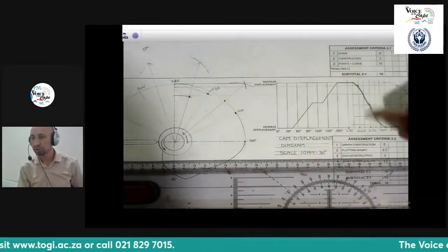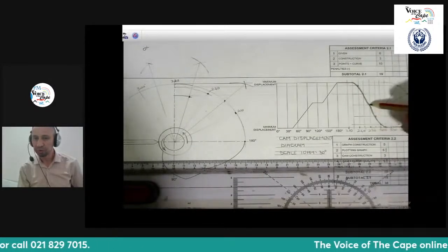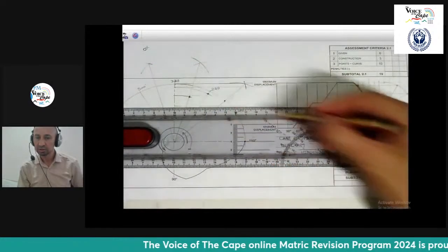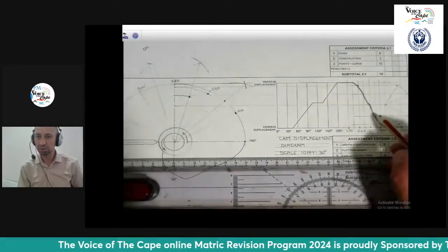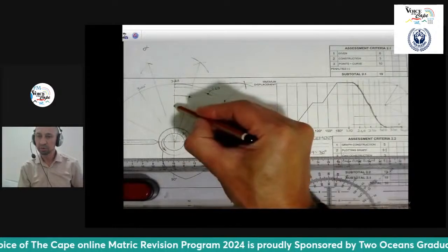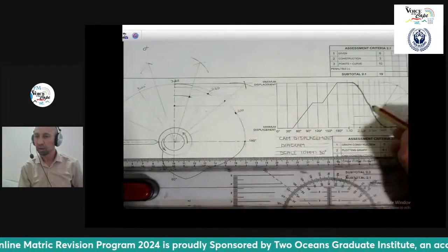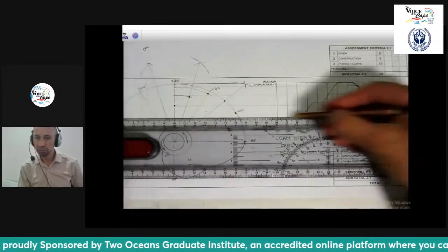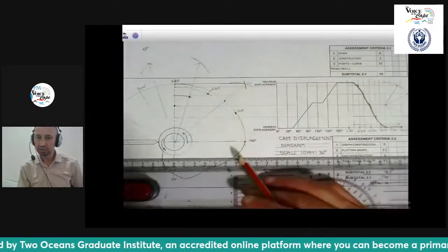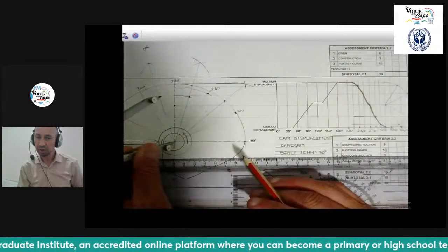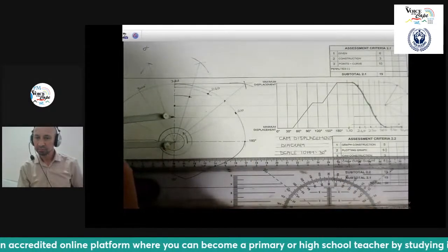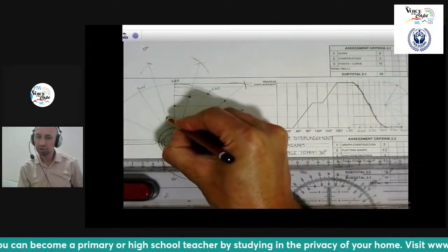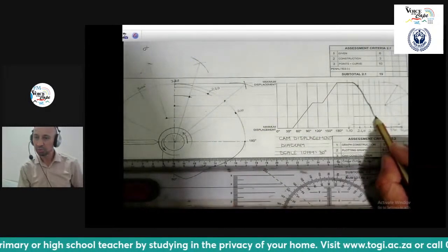Now I'm going to drop down to my midpoint here, which is perfectly on my 270. And that's going to be just straight on this line here. So that point that you see there is the actual 270 point, which you're going to plot there. And then it drops down further to this point over here, which is midway between 270 and 360, which is going to be this line. And then you just transfer that point onto this line. And you get marks for all these lines that you show the transfer of the points. You get marks for it.